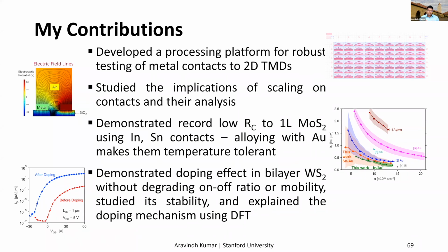We want the damage reduction layer to be low work function, so it's going to be very easily oxidizable. So you want the capping layer to be immune and protect the underlying layer from oxidation. I would say platinum, palladium, nickel are good candidates because they are relatively stable, but they're also CMOS compatible.